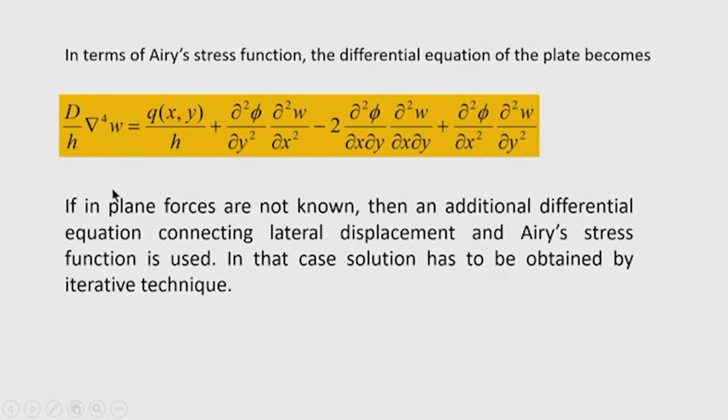The terms are del⁴/del x⁴ plus 2 del⁴/del x² del y² plus del⁴/del y⁴, equal to q by h, q is the distributed load, plus del²phi/del y² del²w/del x² minus 2 del²phi/del x del y del²w/del x del y plus del²phi/del x² into del²w/del y².